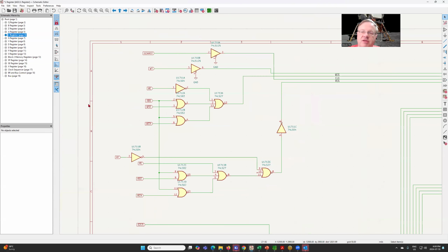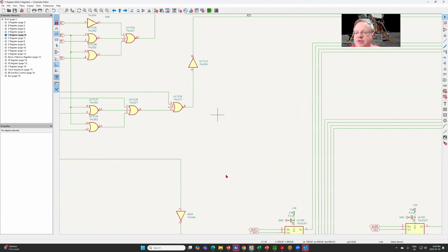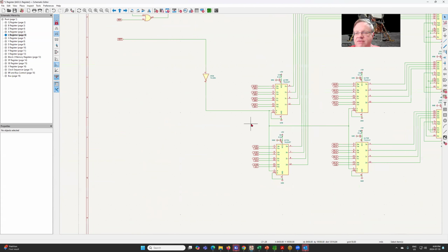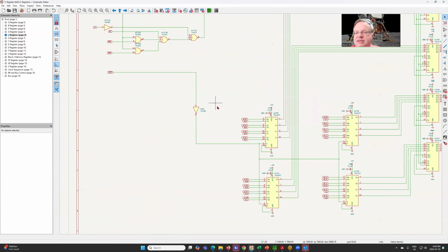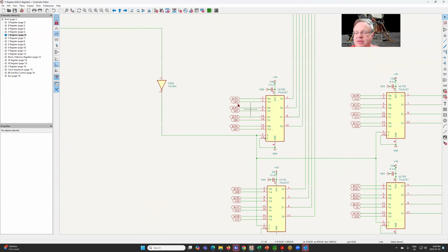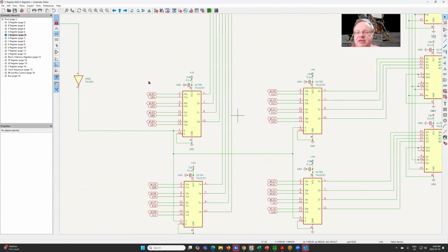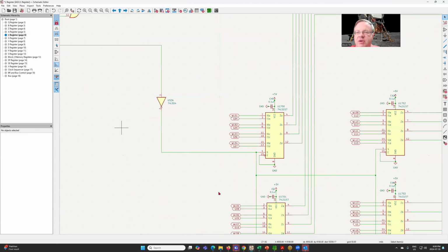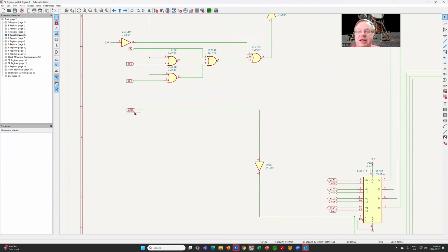Okay, back to the L register. What we have here are two selectors, and this has been simplified because there are only two cases. Either we load data directly in off of the write lines, so WL01, WL02, 3, and so forth, or we load the contents of the G register, through write lines 1 and 2 here, depending on whether we are executing that G2LS control pulse.